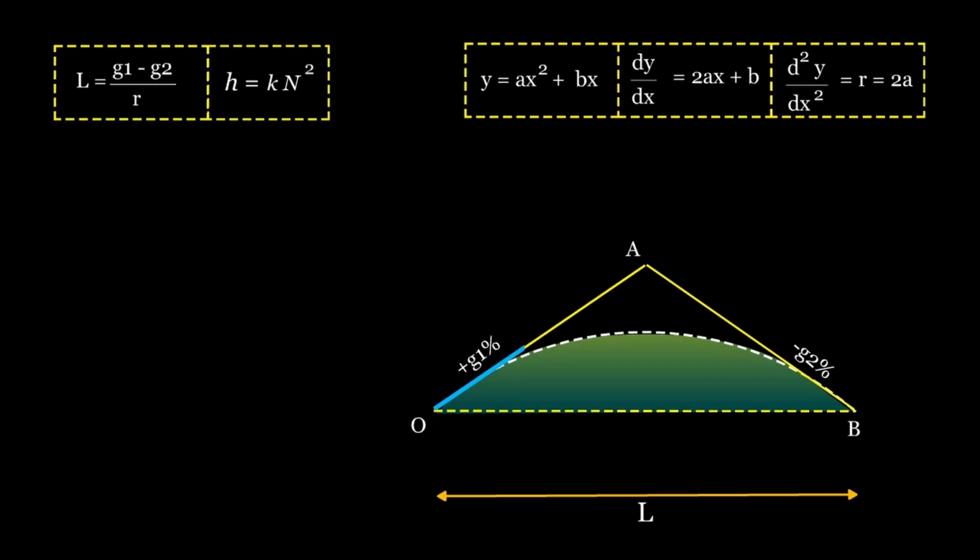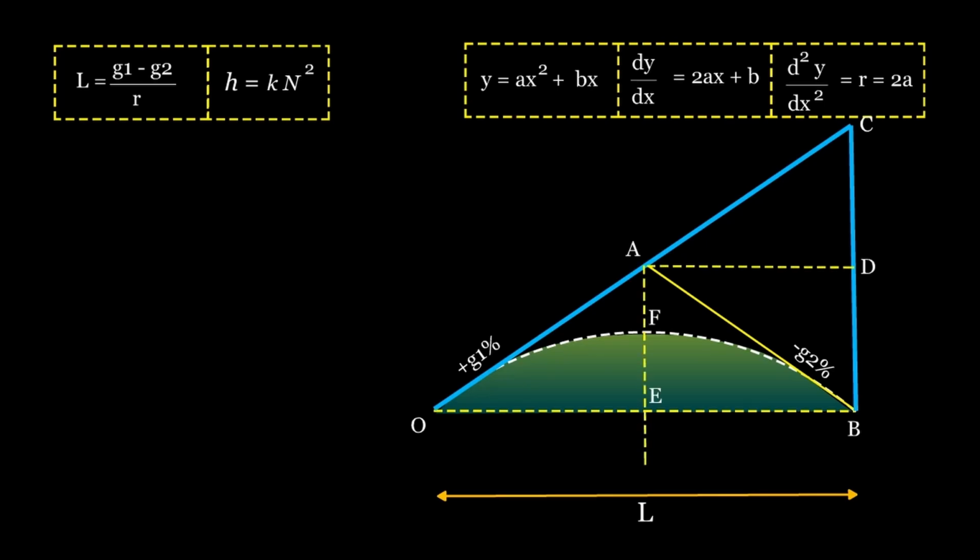Deriving the formula for k. To find k, we extend the tangent g1 to point C directly above B, then draw a horizontal line CD and a vertical midpoint line FEG. The length of the chord at uniform intervals is L. The number of chords at each side of the grade is n numbers.